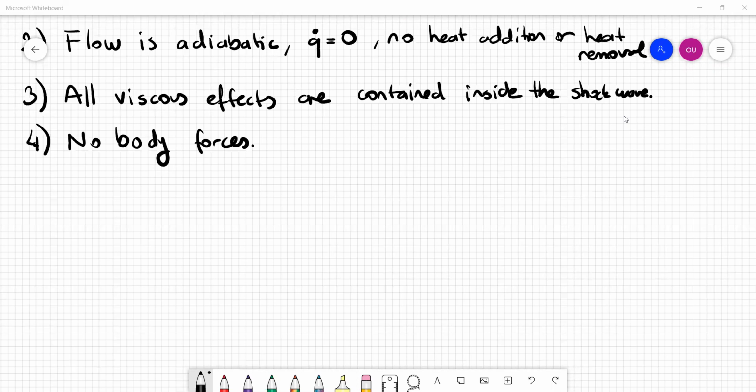So then how can we fly at Mach number, I don't know, greater than 2 or 3? Yes, it depends on geometry, but won't the flow always have a tendency to go subsonic? In some places, and geometry determines the shock wave structure. There is not going to be a single shock wave in reality. There will be multiple shock waves. So the geometry determines the shock wave structure and the number of shock waves, their angles, and depending on that, that determines whether the flow is going to be subsonic or supersonic in different regions around your vehicle.